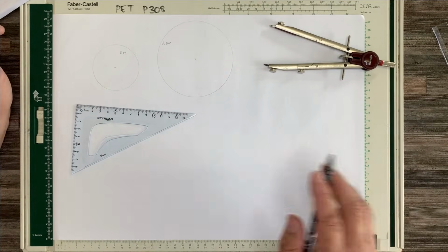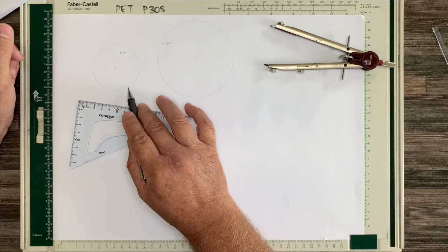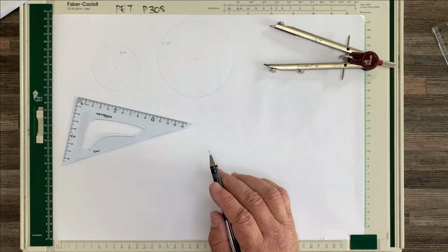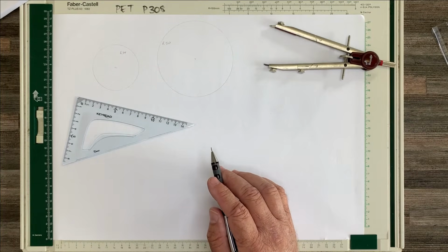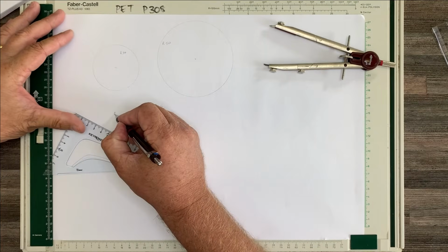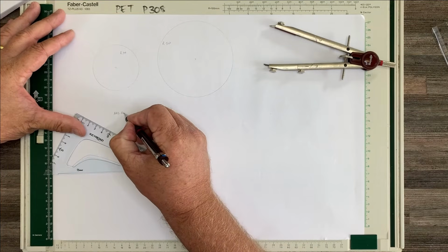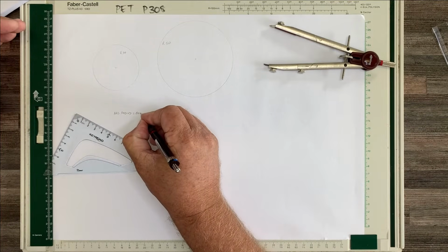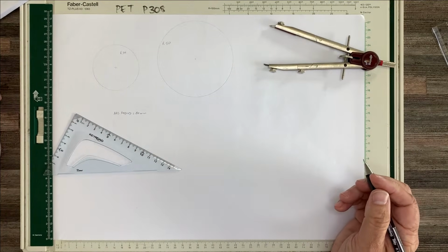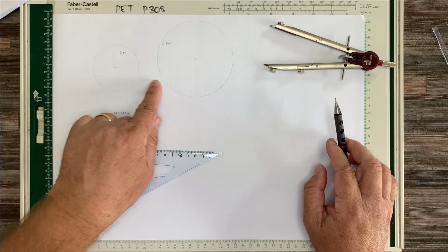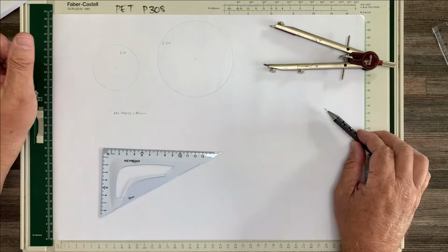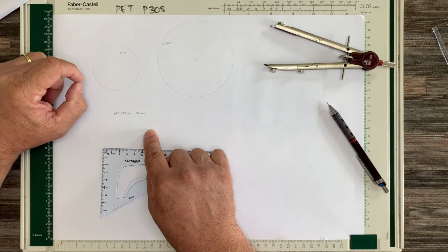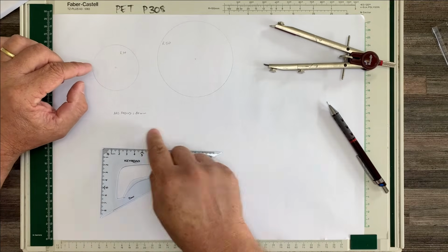All right, what we'd like to do is draw an arc that goes at the bottom, that is facing upwards, and that joins those two, and that must be a radius of, well, let's make it 80 millimeters so it doesn't get too big. So that arc must go here. Now we want to find the center point of that arc. We know that if the arc is going upwards, the center point will be below it, somewhere in this position.